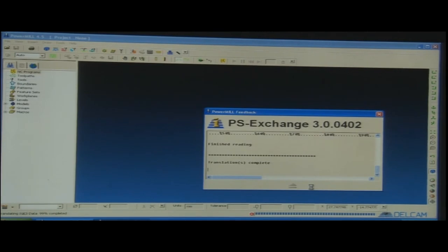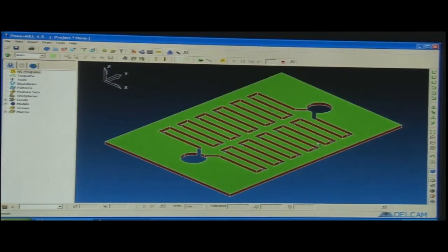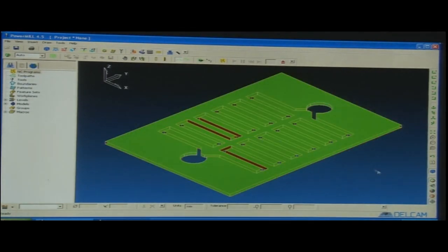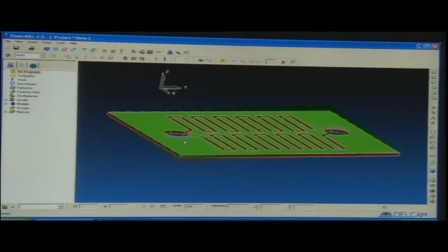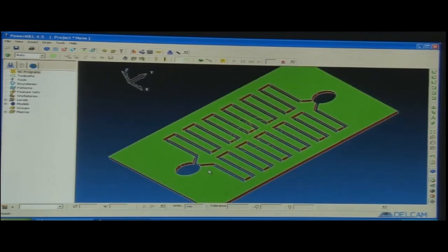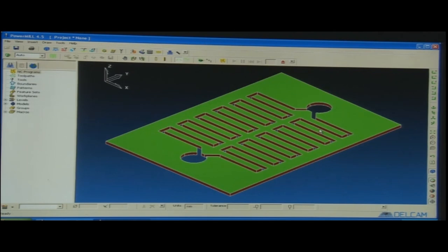So, we have clicked here, and it is importing the CAD model. This is the CAD model on which we will see how we can work. This is a simple IGS CAD model for which we would like to generate a code. You can see here that the part programming and the particular area can be worked upon. For the terrain profile as well, the program can be made.